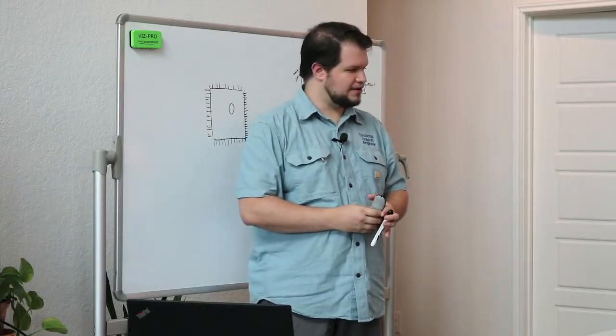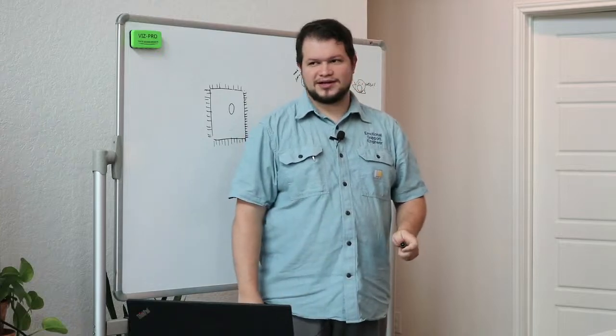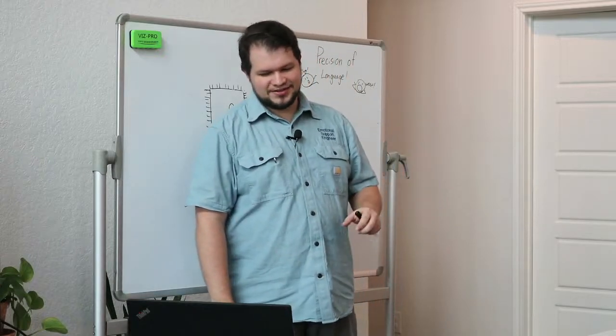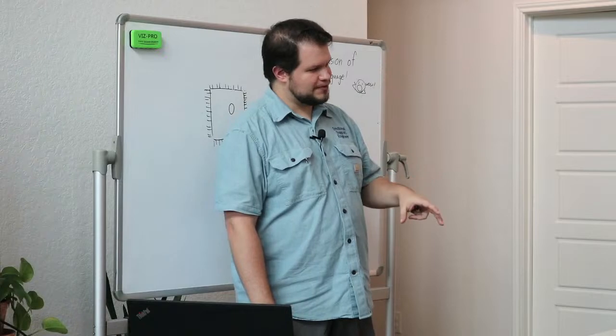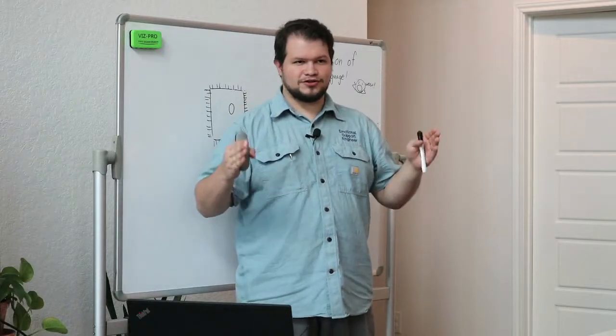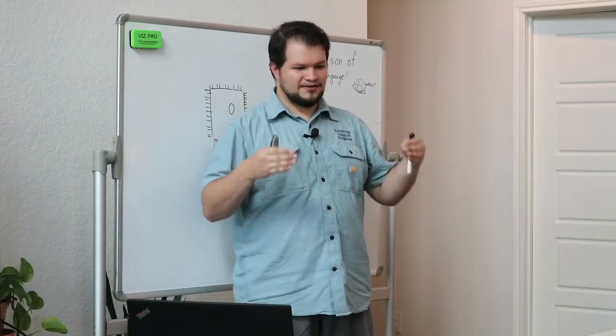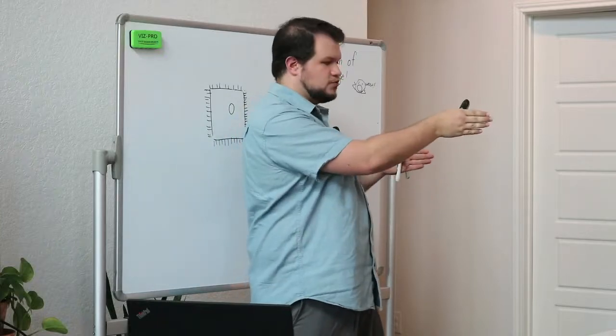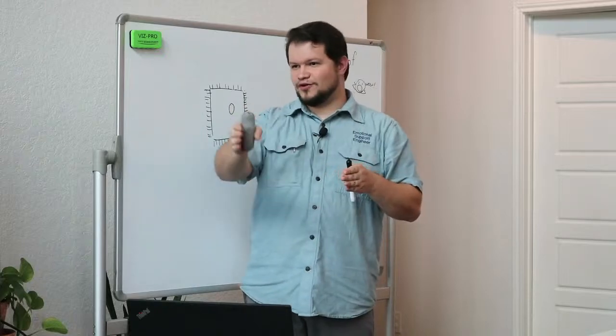Is there anything to add on IMUs? I know IMUs have been a hot topic. The internal IMU, what we have had experience with in this last year at least, is defaulted to robot-centric drive, meaning that it looks at the front of the robot. These are the front wheels, these are the back wheels, that way is forward. If I turn, that way is still forward. It doesn't matter where I'm looking, the front of the robot is forward.